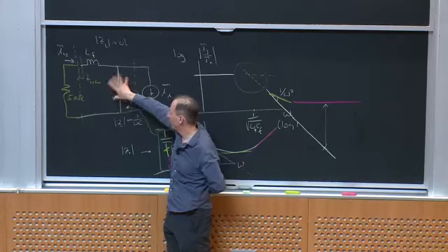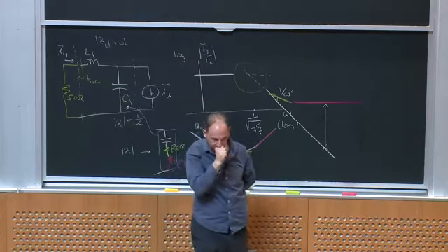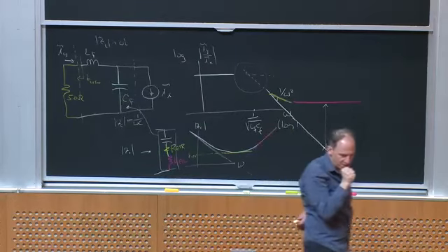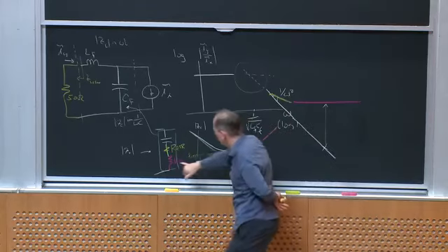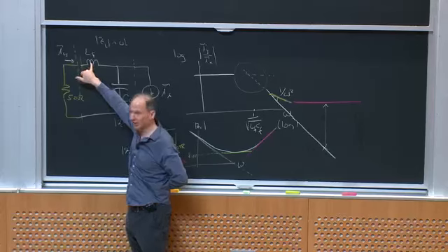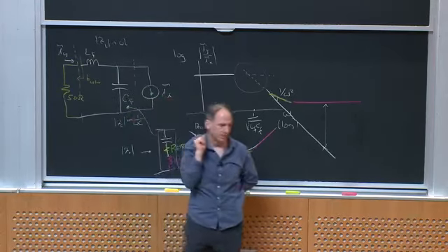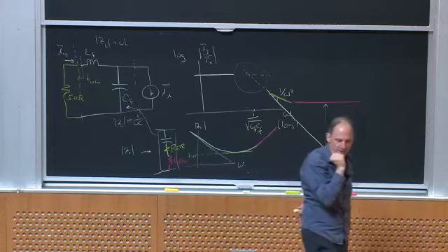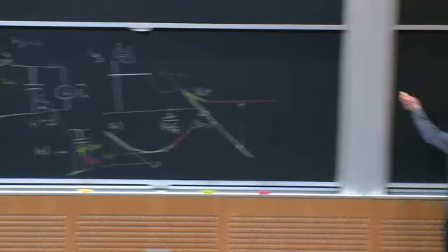And if I have multiple components, by the way, I can get resonances between them, but that's another story. Okay? What else can I do? I might say, well, okay, if I'm limited by ESL, I will use a bigger LF, but you're still only getting a divider that's a proportion between these two, the ratio of those two. If I want really more attenuation, what I can do is do a higher stage filter.